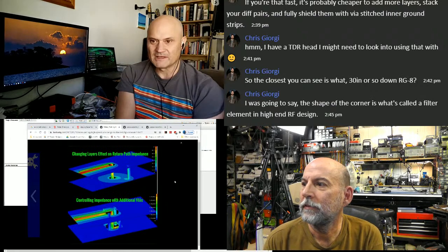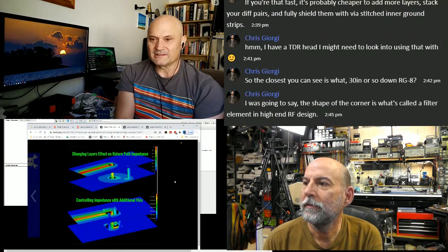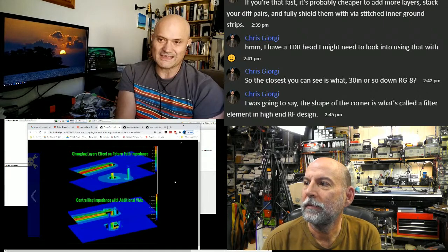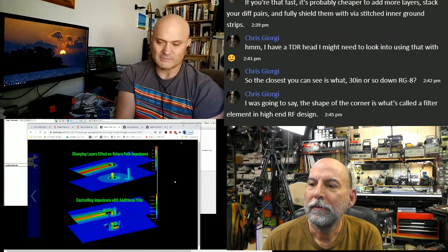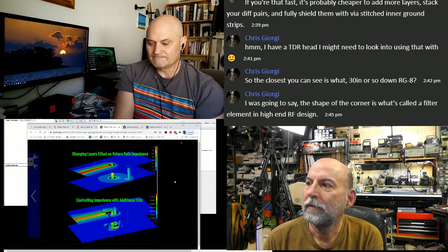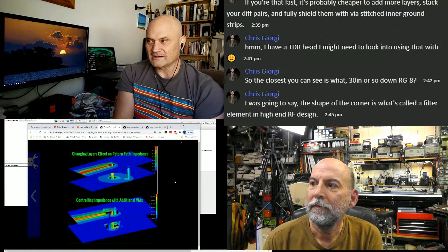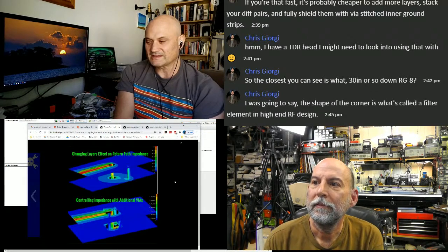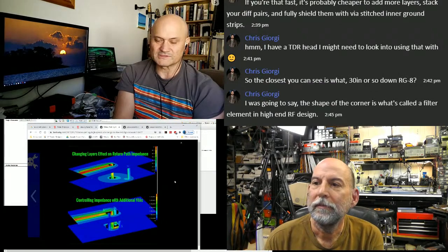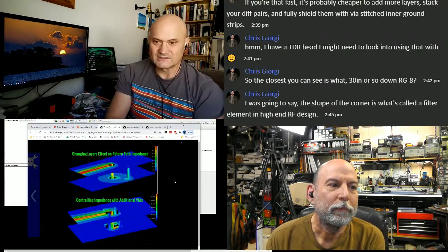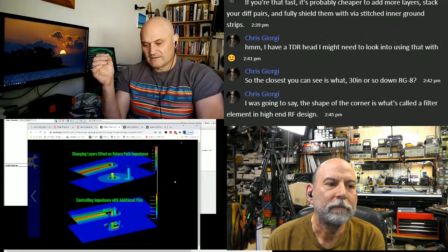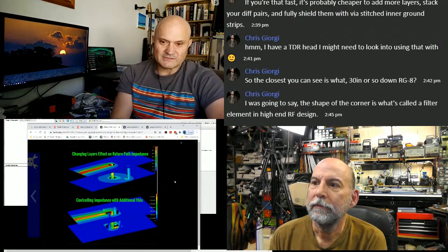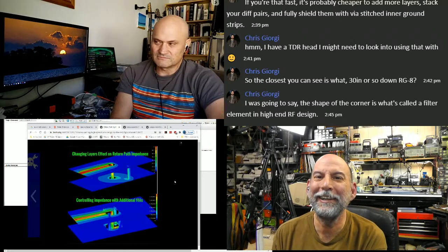This is why in the original PCI spec, not even PCIe, I'm going way back to the 90s when PCI came out, 33 and 66 megahertz parallel PCI bus on computer motherboards. The first rev of that spec, all the boards were still through-hole pretty much for the connectors. In fact, even today, PCIe, most motherboards still have through-hole connectors, and there's ways of mitigating signal integrity and reducing reflections even with through-hole connectors. But we were only talking about a 66 megahertz clocked bus, which is pedestrian by today's standards, right?